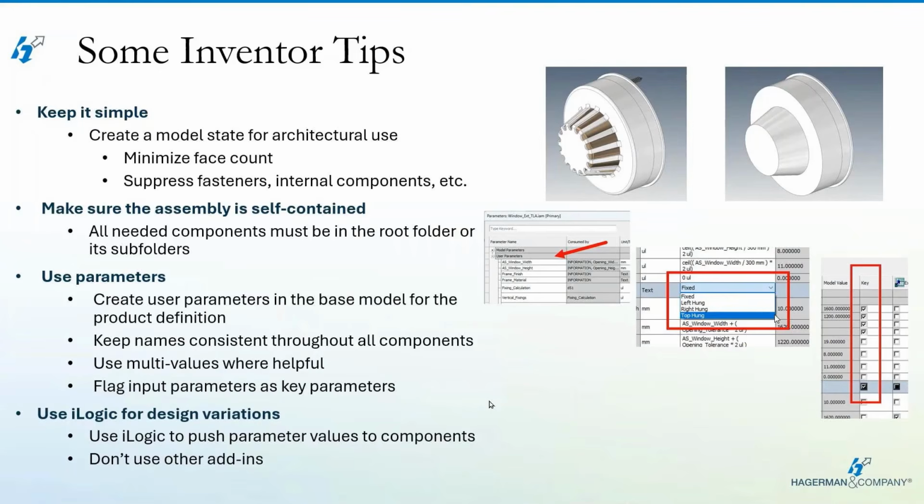And then finally, there's one more click on there. Make sure that you've checked the file before you publish it. Make sure to flex it through some changes in values at the Inventor level. That way you can be confident your Inventor assembly is going to work before you start worrying about adding the information that the customer is going to see.